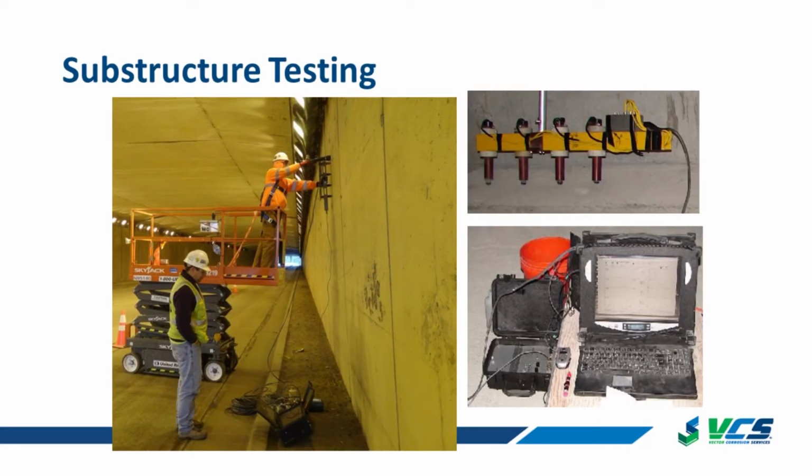As I said before, not just decks, right? Substructure elements. This happens to be a tunnel section, and we're doing the impact echo on a handheld device and doing it up and down the walls, looking for deteriorated areas. And so here's the sensor array and a computer acquisition system. One person, myself, working and somebody just watching, as all work has to be done like that. What we're out there to find is where the deterioration in this wall is.